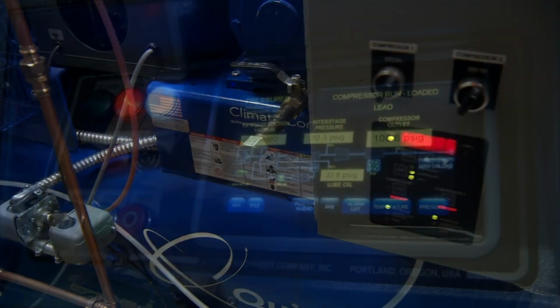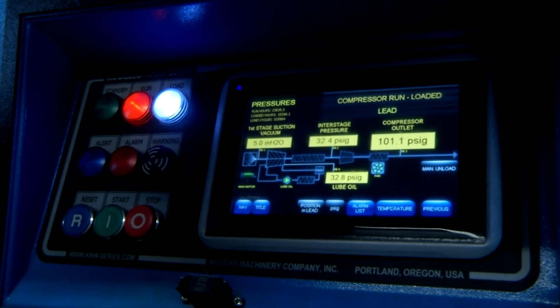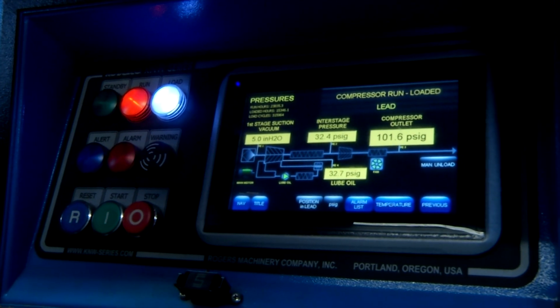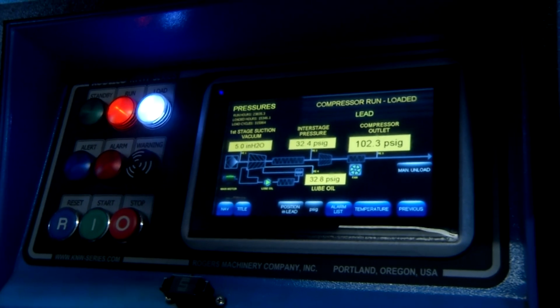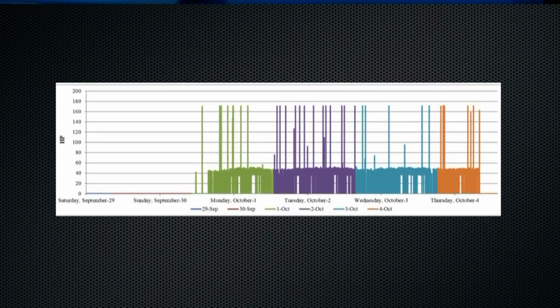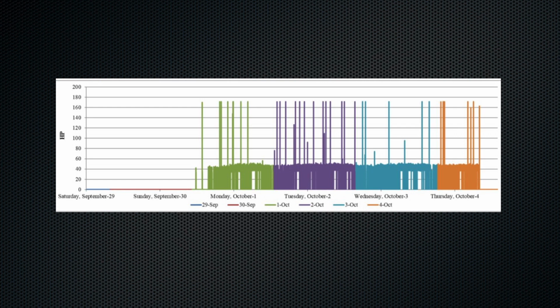When a compressor brings a system up to pressure, it then needs to idle. So it operates part of the time loaded and then the rest of the time unloaded. The energy used when unloaded is a big waste, and therefore compressor selection and how it operates in an unloaded mode is key. The reason I bring that up here is one of the best things about recips, especially for